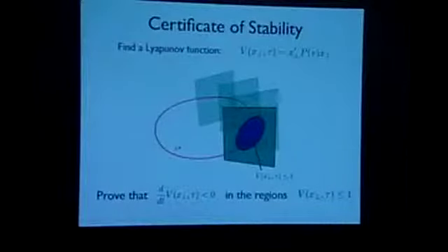Question? Yeah. So the statement you wanted X-perp to be stable, it's not clear to me. It may well be the case for reasonable controllers that portions of the limit cycle diverge locally. That's fine. So why do you then say X-perp should be stable? But not necessarily stable over the entire cycle. It can go away and come back again, and when I come to the description of the Lyapunov analysis, our Lyapunov function will grow and contract at the same point. Yeah, but a perfectly reasonable failure mode for a walker is to go faster, faster, faster, and blow up. But that wouldn't be stable over one footstep cycle. It can, within a phase, go away and come back.